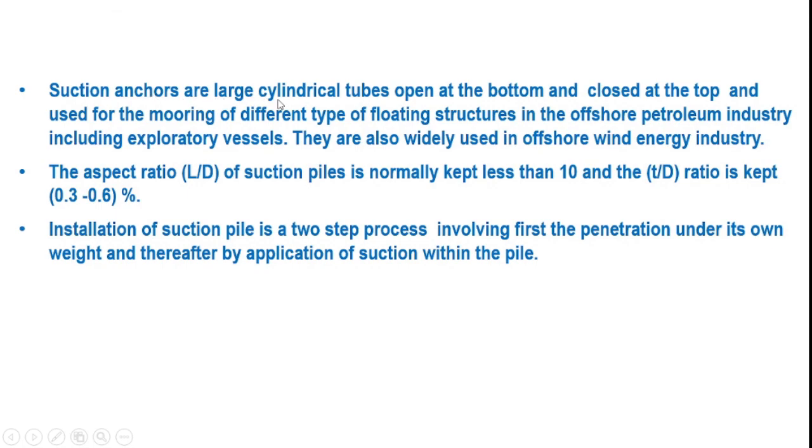Basically, suction anchors are large cylindrical tubes open at the bottom and closed at the top and used for the mooring of different types of floating structures in the offshore petroleum industry, including exploratory vessels. They are also widely used in the offshore wind energy industry.